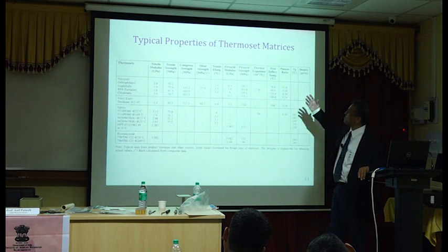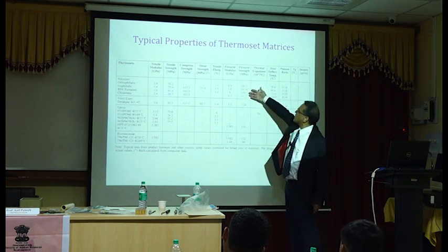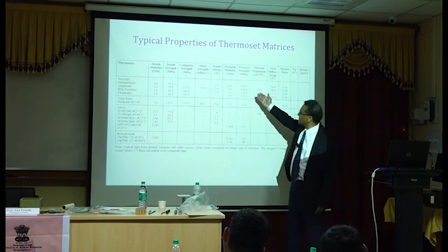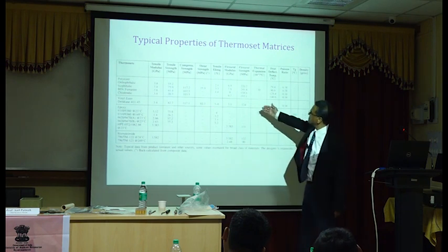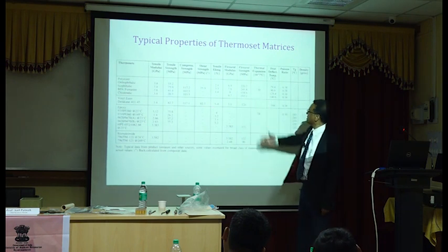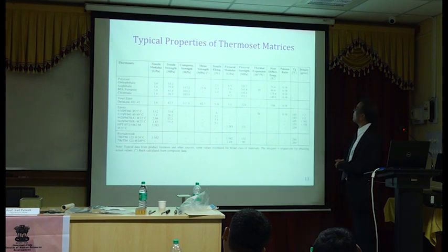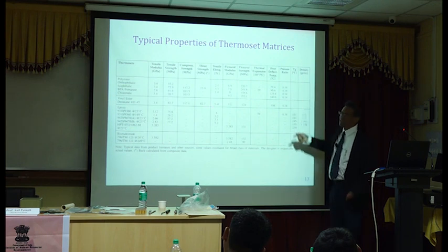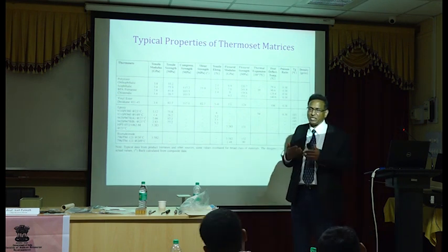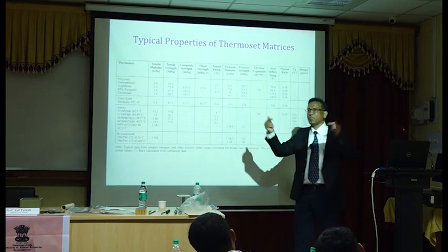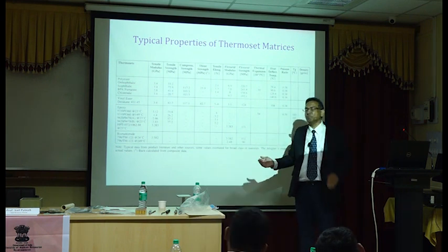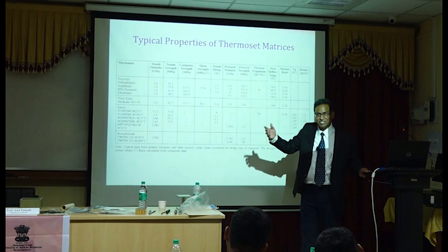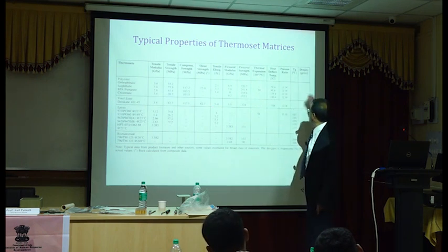I say, okay, my flexural strength, 220, or about 200 MPa, which is not bad actually. It's much better than concrete. And then you have those numbers. Poisson's ratio is slightly higher than steel. So it's 0.38. That means it will expand laterally much more than steel. That's what it means. Does it make sense? You apply axial load, it will expand laterally more than the expansion of steel laterally. Does it make sense? So simple concepts. Okay, that's good.